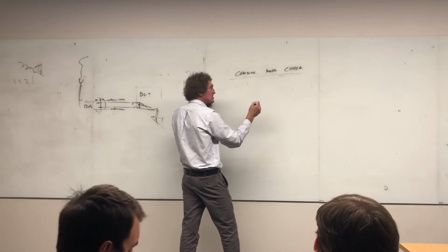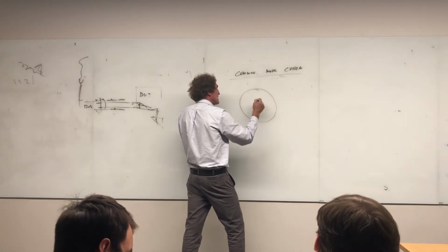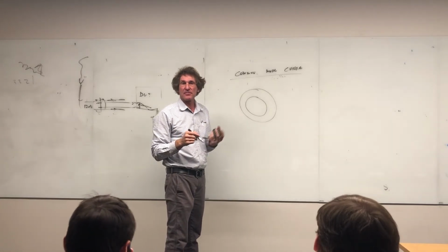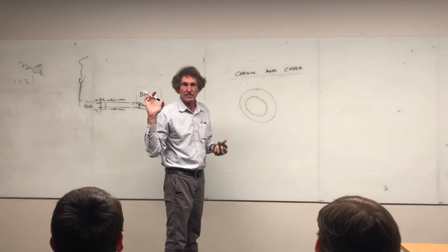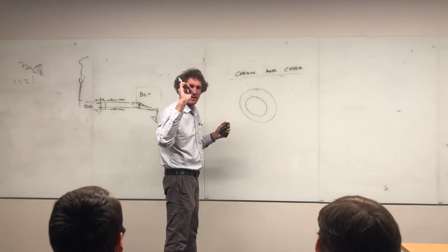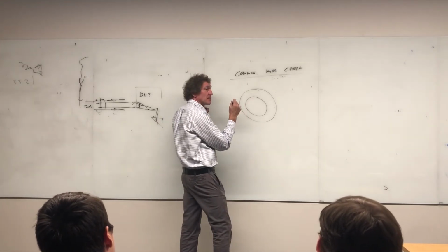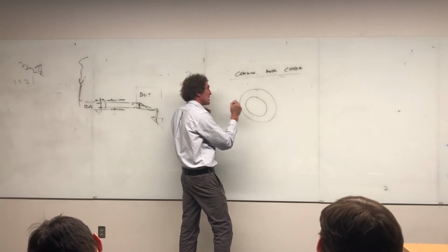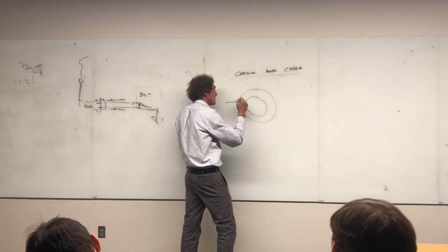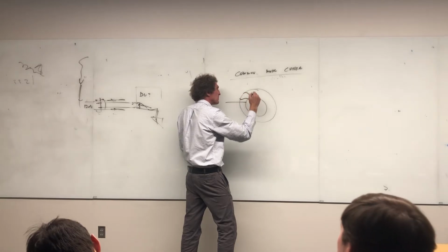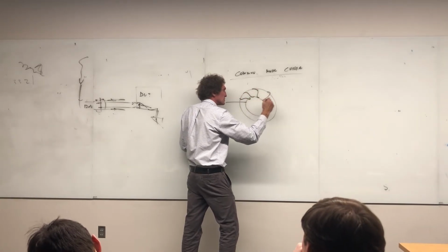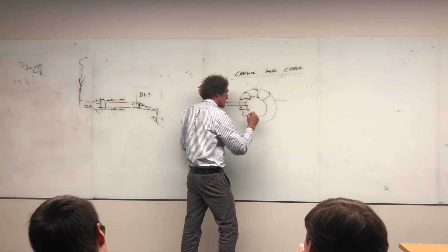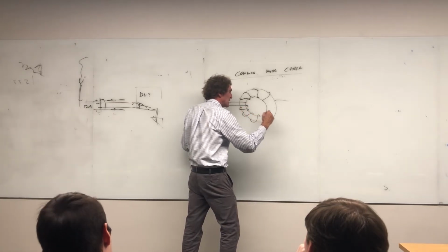So this is a common mode choke. It looks like this, and we build these things all the time. You take a piece of ferrite, it's really a ferrite donut. That's all it is. And we have them upstairs. They're about this big. You can get them any size. You take the wires for your input voltage or current and just take them through like this, and this one, like so. And what you're doing is making a transformer.